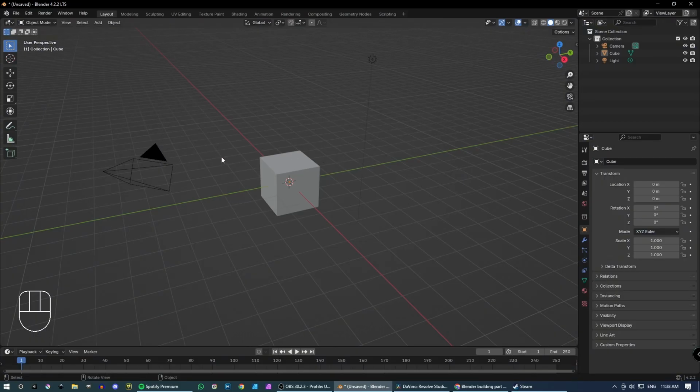When you open Blender, you will have this scene. I select the cube and press Ctrl I to invert the selection, then I press X to delete everything. The first thing I like to do is to make a basic block out of the building. This helped me to get all my ideas into Blender without spending too much time on unnecessary details. I like to keep it super basic. This allows me to try different ideas and see how it looks.